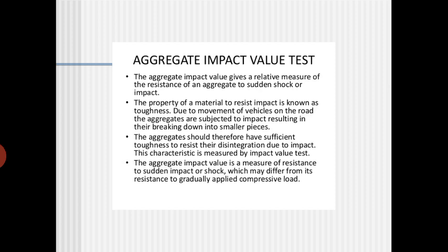So, due to the movement of vehicles on the roads, the aggregates are subjected to impact, resulting in their breaking down into smaller pieces. The aggregate should therefore have sufficient toughness to resist disintegration due to impact. This characteristic is measured by the impact value test. The aggregate impact value is a measure of resistance to sudden impact or shock, which may differ from the resistance to a gradually applied compressive load.